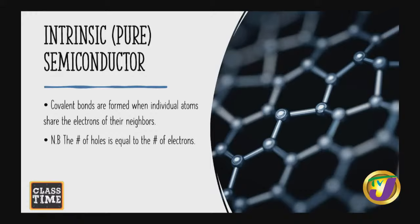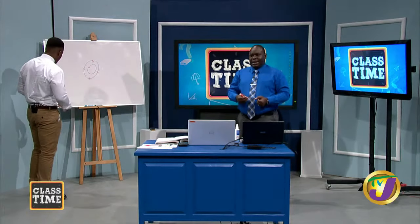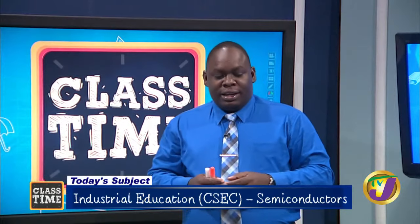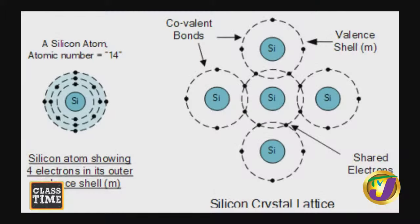Since it only has 4, it is not going to be giving up any electrons, and it is not going to be readily accepting any electrons. And that is why it is so hard to work with intrinsic semiconductor materials. Now, covalent bonds, a very important terminology. These are formed when individual atoms share electrons of their neighbors. So that is what covalent bonding is, students, where you have individual atoms sharing the electrons of its neighbors. It's very important to note that the number of holes is going to be equal to the number of electrons.